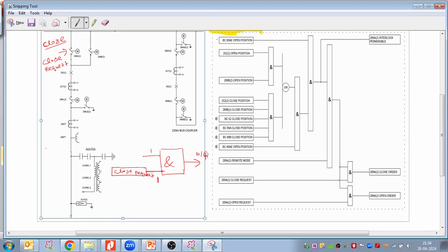So what is my criteria now? 252 will be open. And please keep in mind, this is my double main bus bar scheme. Sir, can we directly close it now? No. We cannot directly close it just because of zero potential difference. I have no position of the breakers. So first of all, we require the breaker positions, to know whether we close the isolator or not.